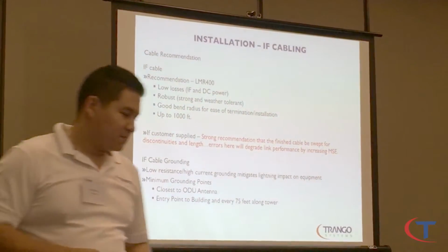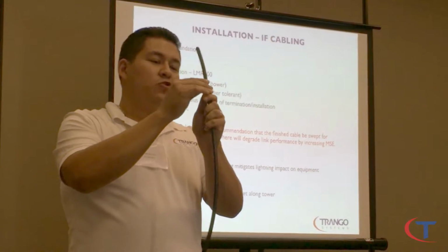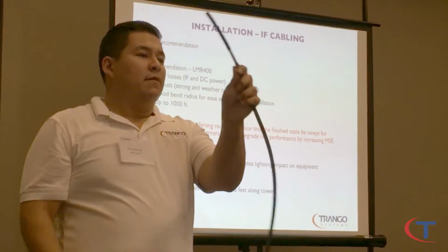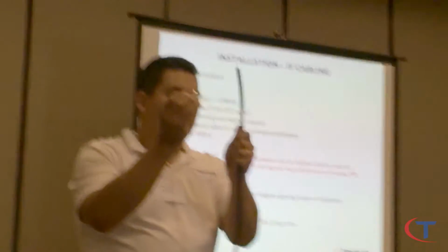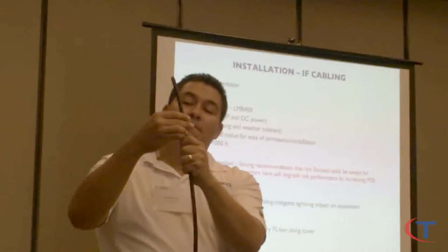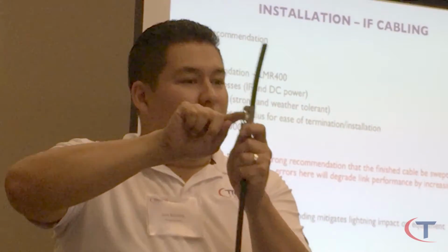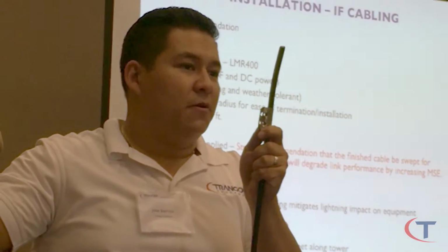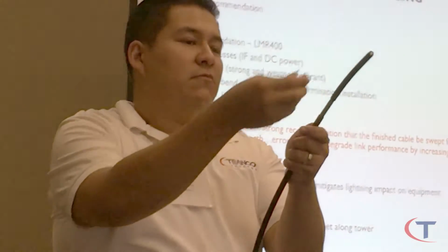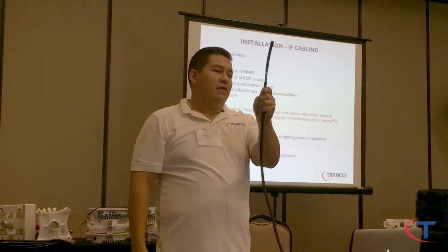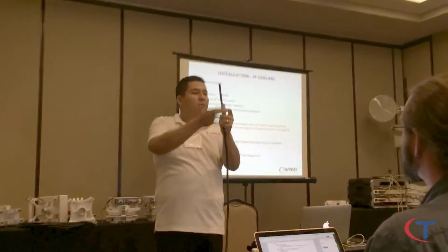Now inline means you're going to have one of these. You strip the cable, peel it like that. This is an inline ground. This goes directly in here. Then you squish it, and you have your grounding cable going to the actual tower. So is that like a vampire tap? Yeah, you strip it and then just clamp it to the shielding. It's stripped, then you clamp it in there, and there you go.